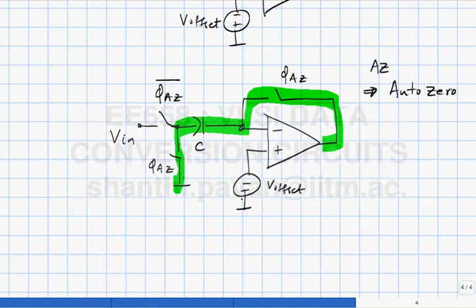So to measure, you need to reconfigure the preamp in some fashion so that one of the voltages naturally happens to be V offset. Okay? Grab that V offset and store that on a capacitor. Right? And once you've stored it on a capacitor, now you know what the offset is. So it's equivalent, and we know that if you don't draw any current from a capacitor, it is the same as a battery. So all that we need to do is connect the capacitor in the proper orientation. Alright? And you will find that you have cancelled the offset.